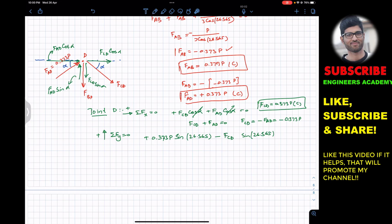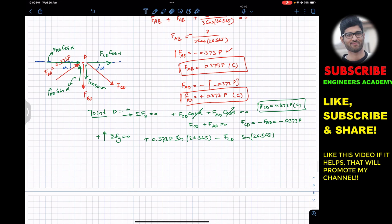So we need to plug in this value here. So this is minus FCD, and since this equation is according to that assumption, we have to put that minus value here. So that will be minus 0.373P, and then we have this acting in the downward direction, and this is FBD. So this is in the downward direction, so minus FBD equals 0, and this will become plus 0.373P.